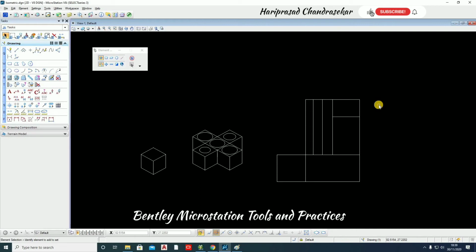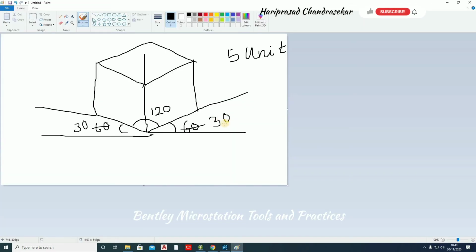Even we also have a perspective view. You can just draw like that, perspective view, 1 point perspective, 2 point perspective. There are no rules and regulations. But for isometric, we must have an included angle of 120 or the external angle of 30. Yeah, I forgot that I mentioned 60, but actually it is 30. So this one, 30.